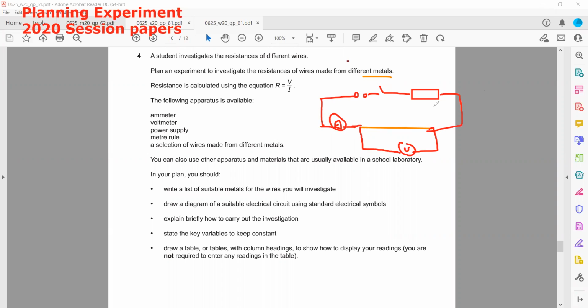So we'll have different sets of results, like some voltage value and a different current value, and using different voltage and current values, we can repeat the experiment for that wire. And whenever we want to find a resistance, for accuracy, if voltage is on the y-axis and current is on the x-axis, the slope represents resistance.